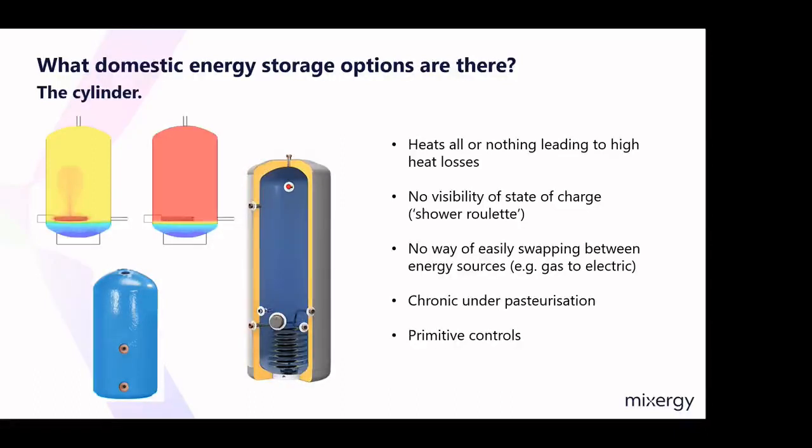But if we've taken a low amount of electricity, so we're only putting in 500-600 watts, if we look at the top left-hand graphic where my cursor is, we're only going to heat a little bit of water. It's not going to be stored as usable water. So storing usable energy as hot water in a traditional cylinder has quite a few drawbacks, unless you have an abundance of power.